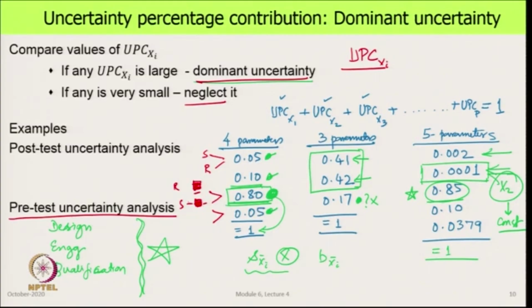And so, it is a situation where you have an apparatus, say for measuring thermal conductivity of a material, and somebody comes and says, please measure the thermal conductivity of this material for me. The first thing you would do is to figure out if the broad parameters are acceptable, and if that is okay, then you come and do the pre-test uncertainty analysis and see what sort of uncertainty you can expect. And if those are acceptable to that person who has come to you, then you go ahead and do the experiment. If they are not acceptable, nothing goes forward, we say we can't do that, something else has to be done.